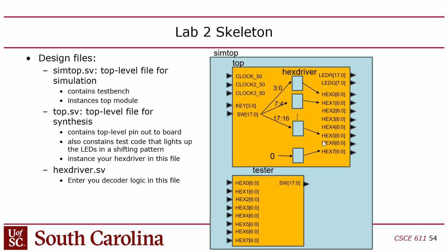Right, you guys remember 7 segment decoders? Right, so you put 4 bits in as a hex value, and coming out you have 7 bits that are going to drive the little displays on the board, okay? So the way I tried to depict this, so SymTop has no inputs and outputs, because whenever you simulate a test bench, you don't actually want there to be any inputs or outputs on the top level of the simulation, because presumably you have code that's setting the inputs, and code that checks the outputs of the design under test, right? So the SymTop has 0, it's just a module with no IOs. But top has the IOs that are specifically set up for the board, so they're named appropriately.